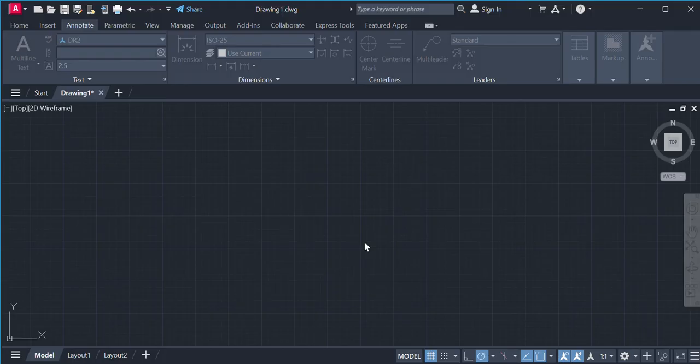If that fixed length extension line is not selected, it means the distance between the object and where your dimensions are, there will be a continuous line, which sometimes tends to look a bit untidy if maybe your dimension line needs to be a bit further away than you normally would have put it, or if you need to align your dimensions, then it might look a bit dodgy. So just do that so that your dimension lines or your extension lines are exactly where the dimension itself is. Then you can click a length of 10. I think it's doable as 10.